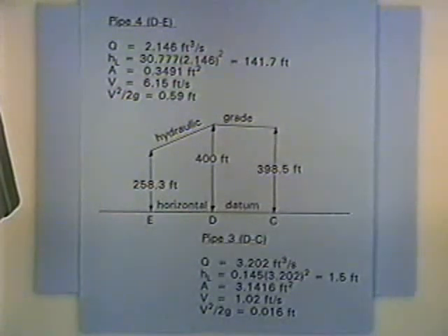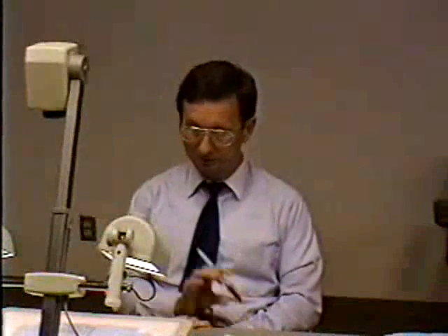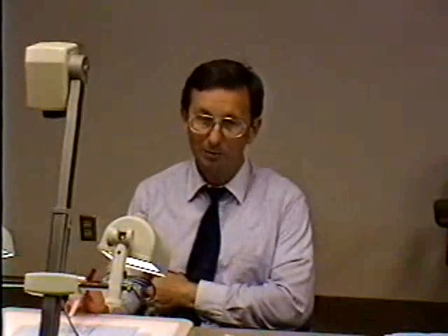Now, a couple things. One thing is that, and this is very common, what I've just presented is the conventional way of civil engineering, both in textbooks and in the process of computing hydraulic grades. But really, head loss is not a difference in hydraulic grade, but a difference in the total energy, which includes the velocity head. And we've sort of ignored the velocity head, and that is a bit of a simplification. But what happens in most systems is the velocity head is relatively minor.